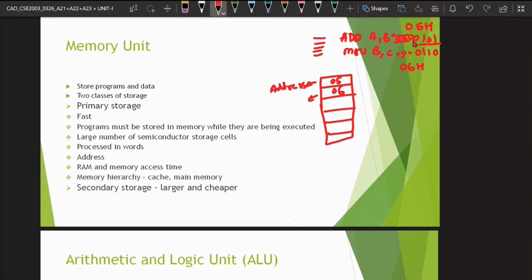So it was an instruction, but once we convert it into object code, it will be a number, an 8-bit number. In hexadecimal we have written 05, or we can write 00000101, or 00000110. So these instructions themselves are the value. You can consider 05 a value.